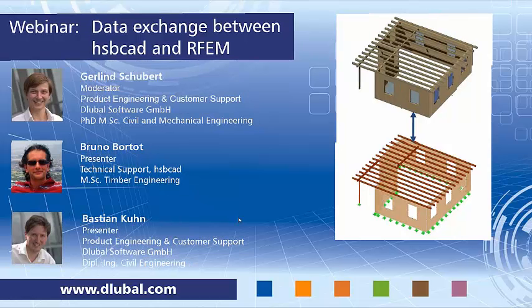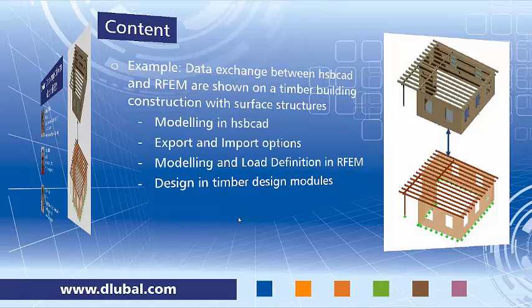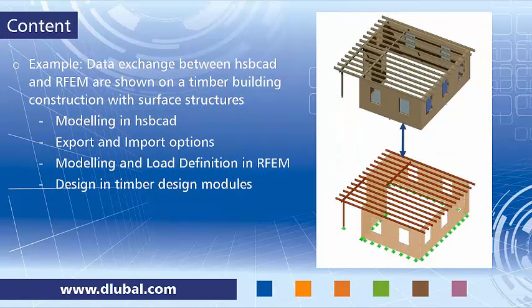The data exchange is shown on an example, which is a timber building construction with surface structures. You see a picture here on the right-hand side. The modeling is done in hsbcad by Bruno. He will also export the model. And Bastian will then take over and import the files into RFEM. He will also do some further modeling and load definitions and finally designs the timber construction.